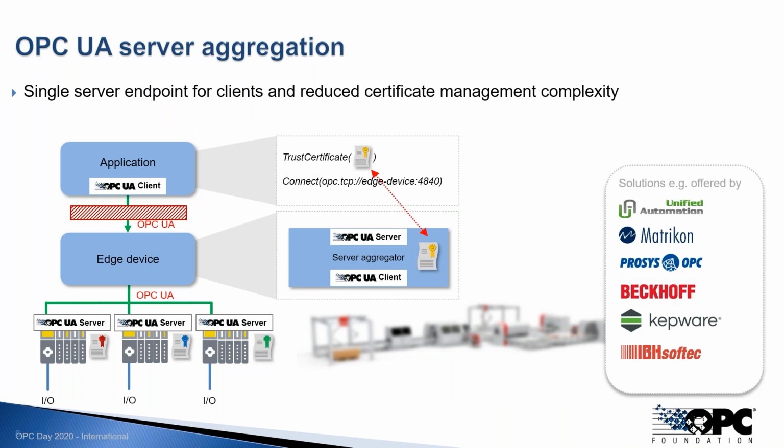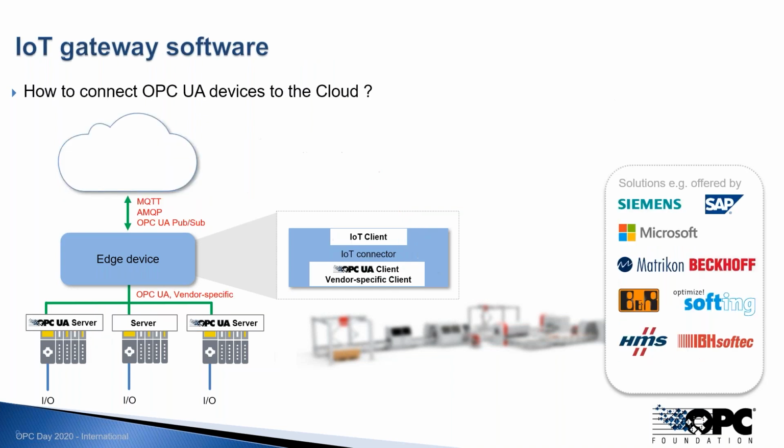As a last point, not actually the last point, but of course, if we are talking about the cloud connectivity, then we don't need to stick to this client server capability. We also could make use of the OPC UA MQTT mapping capabilities for the protocol, or OPC UA PubSub, whatever is easier to set up in the situation of this existing plant, right?